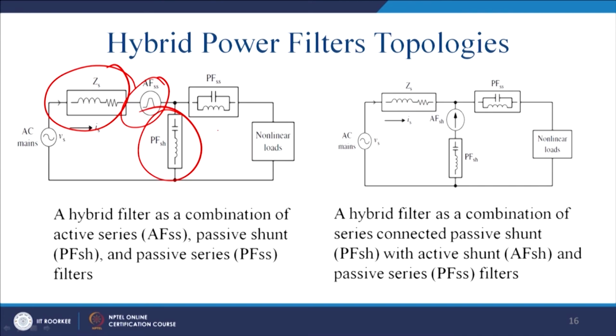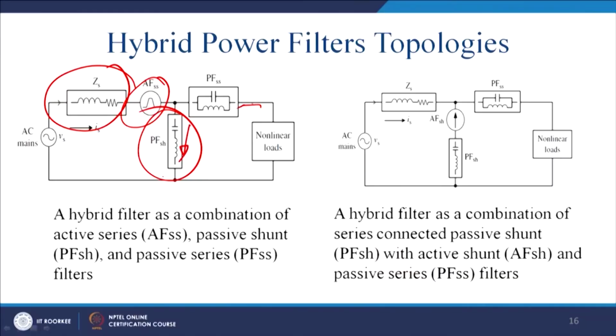Then this entity will have to sink the current; since your fifth harmonic current is less, it does not have a problem, voltage is less, it does not have much current left, and whatever is left out will be blocked. And if you see from this side, this will be blocked and whatever is there will be sunk into this passive filter.